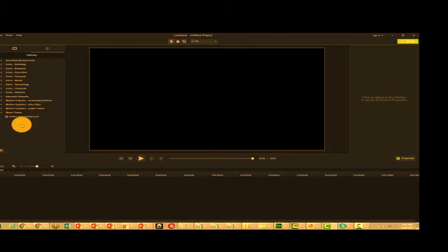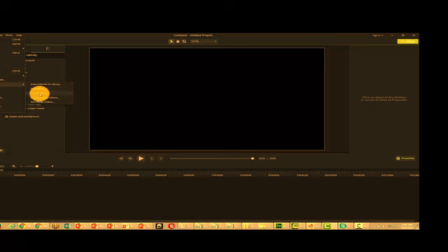So you have to make sure that you've exported your entire library from the computer you work on to your production machine. And you can do that very easily if you just go to the library tab, and then you look for export library. So you're just going to export your library to a zip drive, and then you're going to re-upload it on your production machine.